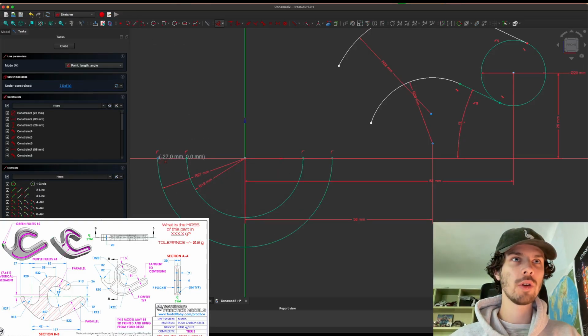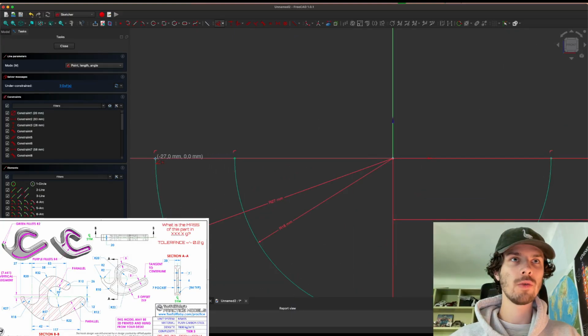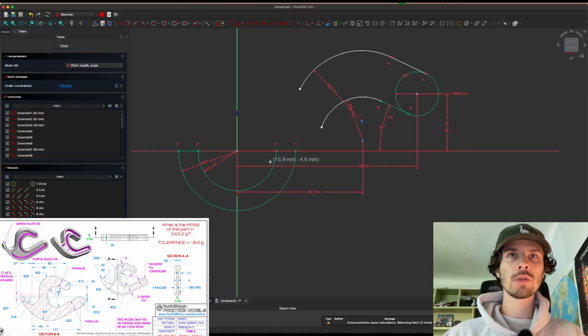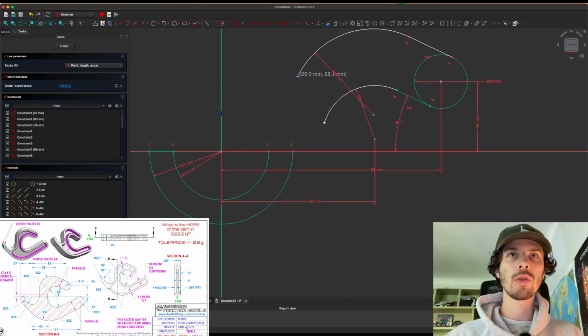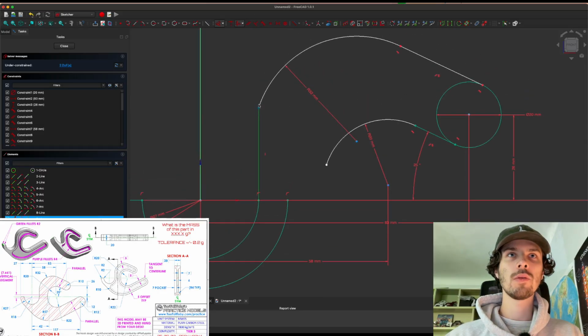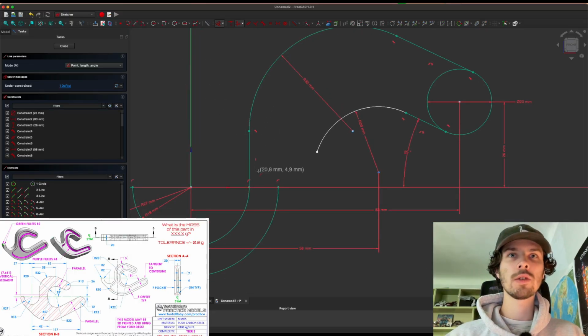Actually, while we're at the shape, let's close the loop. We have these 2 points, they're not closed nicely, so we don't have to do it later. So this shape is alright. We can actually connect it over here. Seems pretty wrong right now, but what we're gonna do is make this vertical by pressing, you can see here, vertical, or just the shortcut V. As well, tangency, we need that. Let's add tangency, great. And a similar thing here. Let's close this loop here.